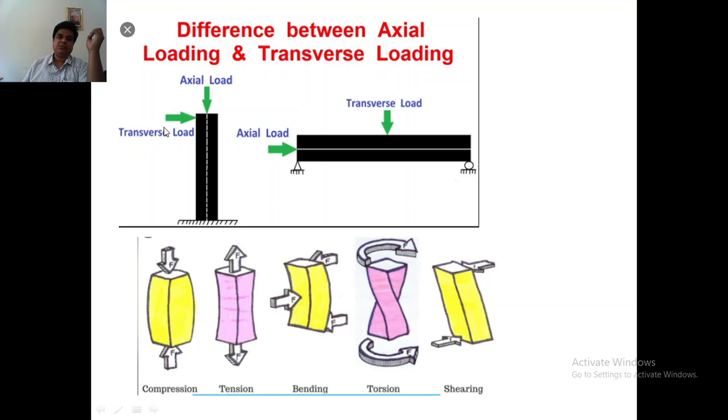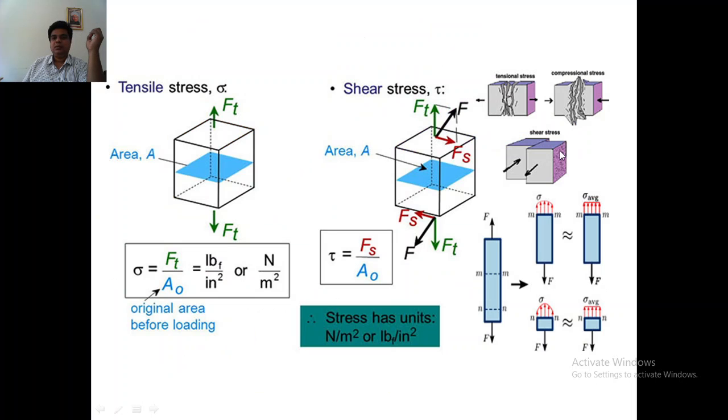So that's why it's called shear load or transverse load. So the shear stress is shear load or transverse load divided by area. Tensile stress or compressive stress is because of the tensile force or compressive force. But the formula remains the same. Stress is force by area.